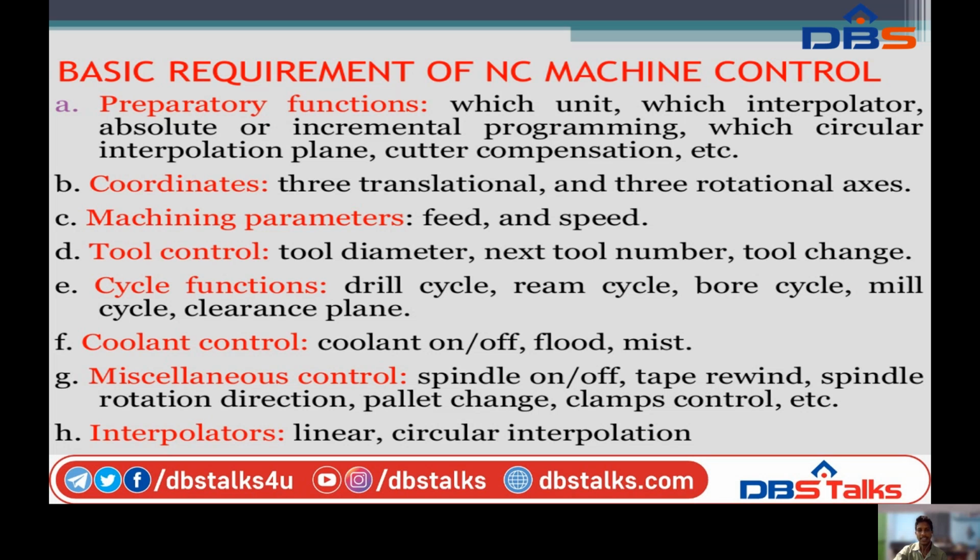After that, in case I am changing from the drilling operation to the milling operation, the milling tool will be 2. Giving tool numbers to all operations makes it easier to do automatic changing by using an automatic tool changer for faster production.